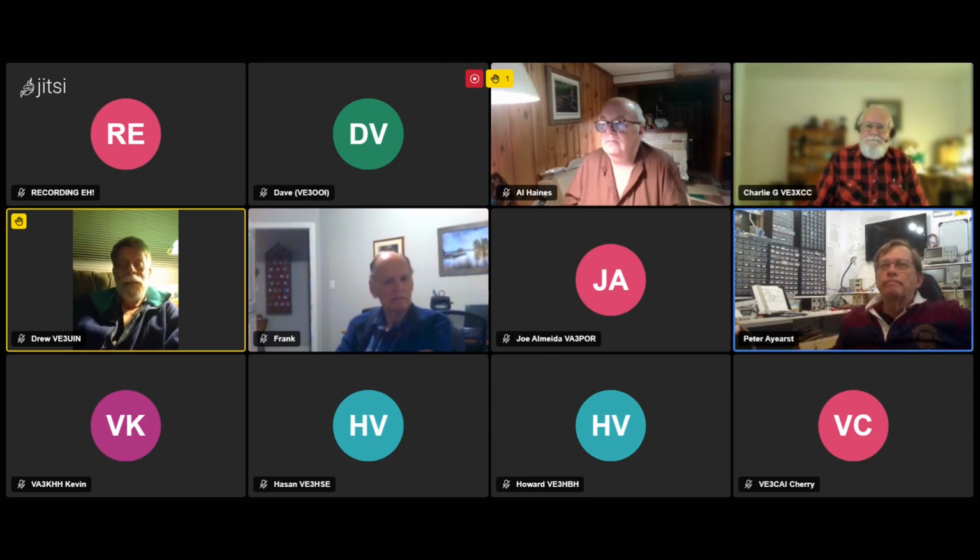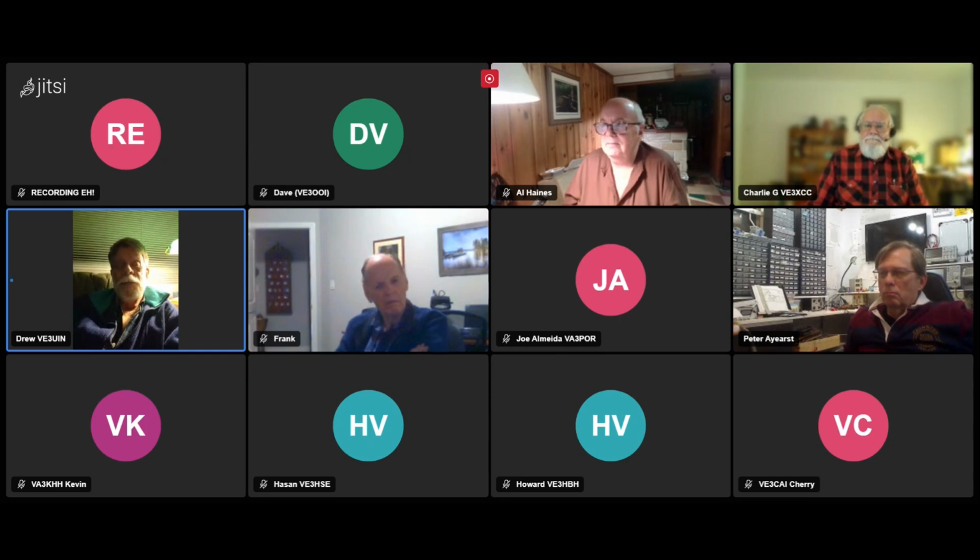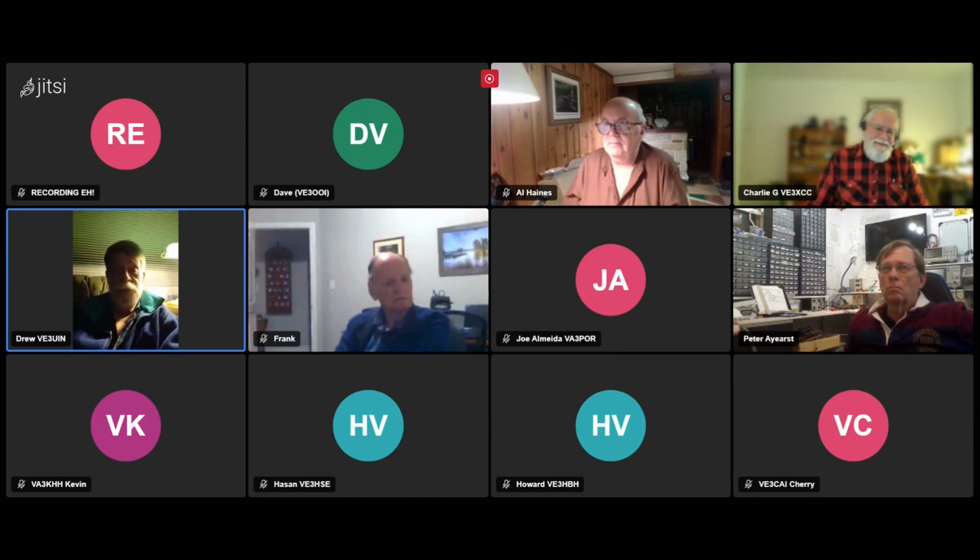Drew. It's interesting that you mentioned the beads and HF. The typical fashion for creating a G5RV was to have 28 feet of 300 ohm go into a dipole, and you would stack that 28 feet with beads, a bunch of them. And there was always a huge debate about whether you needed the beads or how many beads. And some people would simply fill up 28 feet with as many beads as they could get their hands on. Wow. And from what you're showing me, it really doesn't matter.